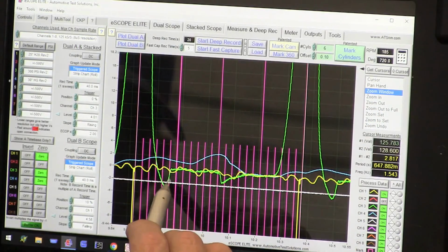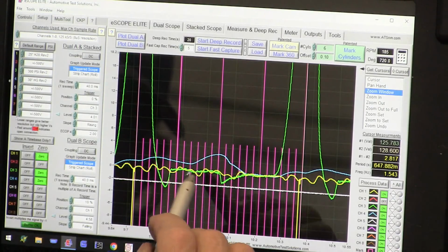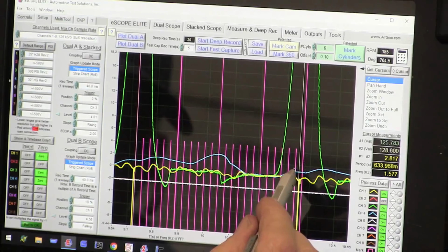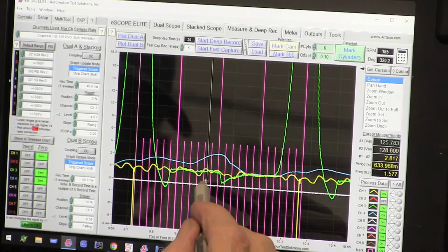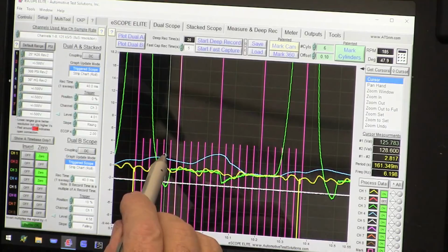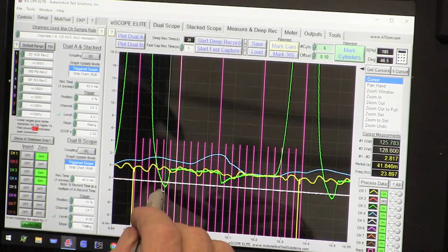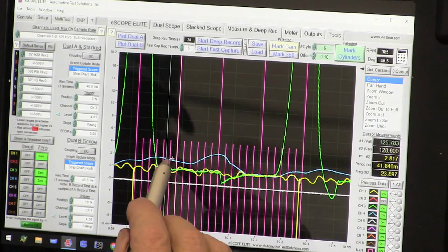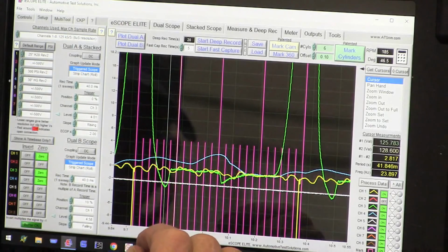We can see that the exhaust is between 30 and 60. That's probably about 50. We can actually measure that. So if we get this cursor here, and we put it on the bottom dead center mark, and we put that at the lowest point. That exhaust pocket is basically 46 degrees before bottom dead center, and that's what I would expect.